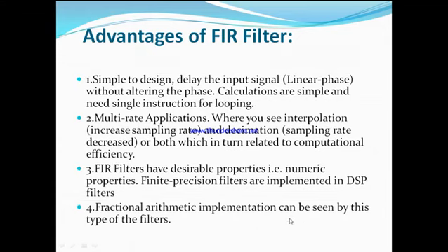For any realization of an FIR system, the first step is to write the difference equation governing the system. After that, you have to write the Z transform for that difference equation. Then only can we realize the FIR system.